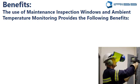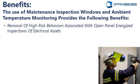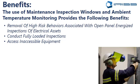The benefits of using the maintenance inspection window and ambient temperature monitoring system are as follows. We remove high-risk behaviours associated with open panel energised inspections of electrical assets. We conduct fully loaded inspections, which is really when we want to do them. We can access inaccessible equipment, so irrespective of how high the HRC level is, it doesn't matter, because the panel remains enclosed and guarded, and I'm not exposing myself to energised work. I'm literally looking through a maintenance inspection window, taking all of my readings and moving on.